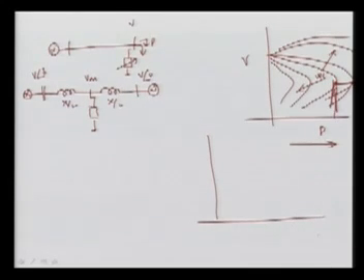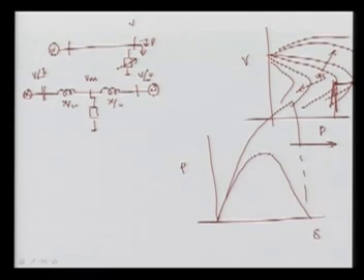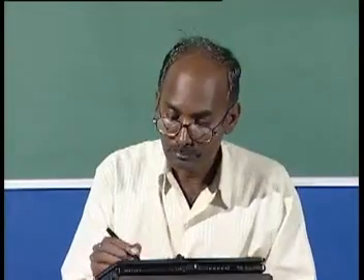For transient stability, it is always an angle; here it is the power angle we normally discuss. So this is your P-delta curve, let us suppose, in the normal case. Now if you are going for the midpoint compensator, the characteristic is going to be double of this, when we are putting the compensator and trying to maintain the midpoint voltage equal to the sending end voltage, a fixed voltage.